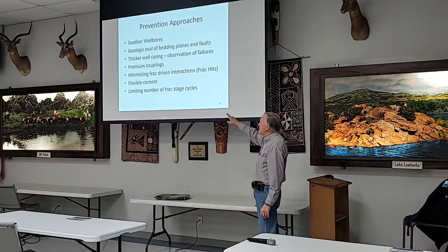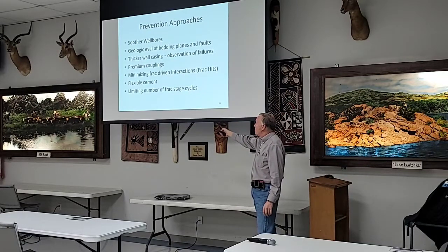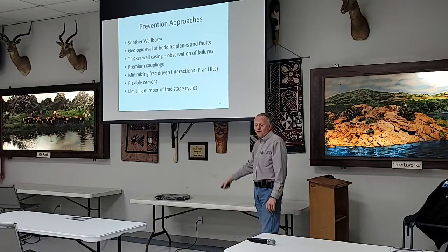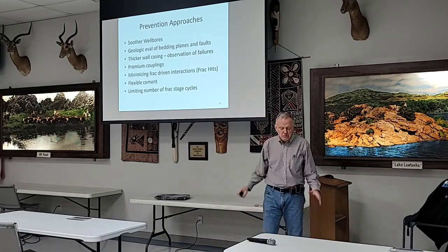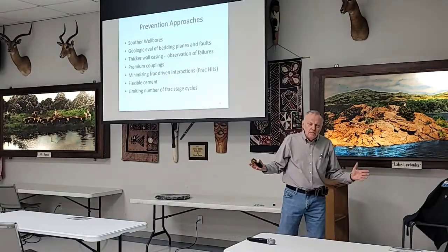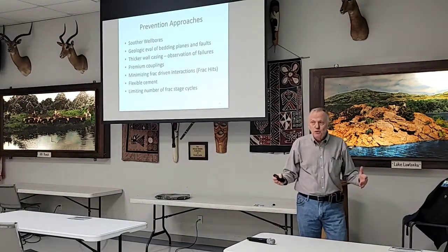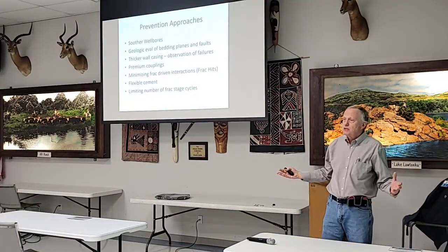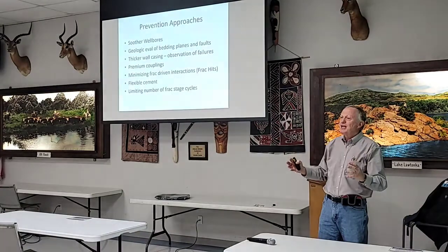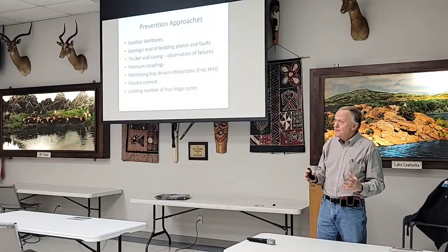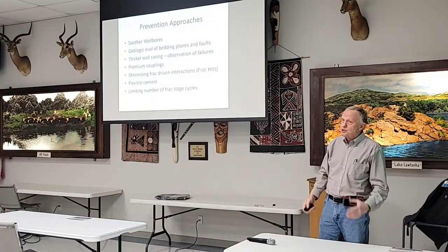Look at flexible cement. Look at limiting the number of frac stage cycles that you get in there. Most people don't want to do that, but we see that when we get into larger and larger amounts of these, all these factors can play together. Sometimes it isn't just one factor that's creating this issue. All right, that's it. If you have any questions, I'd be glad to answer them or try to answer them at this point.